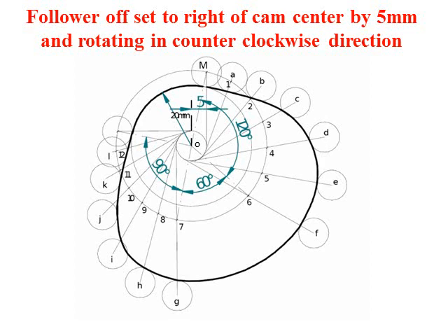Take OM as the base and transfer the outstroke values, that is 120, dwell, and the return stroke. Again, the same process. We have to divide the outstroke and return stroke into the same number of even parts as that of the displacement diagram. After dividing it, extend the lines so that they cross beyond the prime circle. Next, mark 1, 2, 3 on the prime circle wherever the line cuts through it. Next, we have to transfer the displacement diagram value, that is 1a.